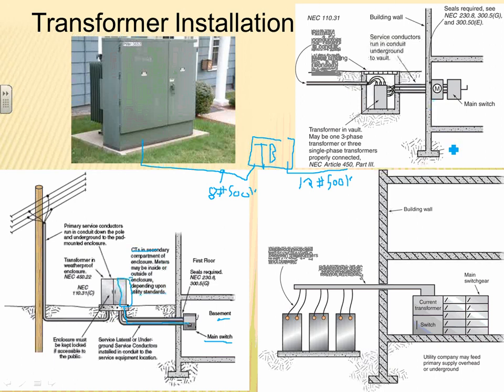Here's another example where this is typically in downtown areas where your meter is going to be your service point. Your service conductor is coming in here, and that's where you stop right at the point. Here's another example. You can have a bus duct, busway, tons of power. If you have tons of power, you can pull all this power into your current transformers, and your service disconnect will be right in here. So these are different scenarios, guys, of bringing the power into the building.